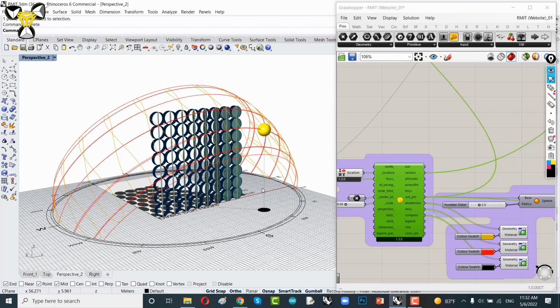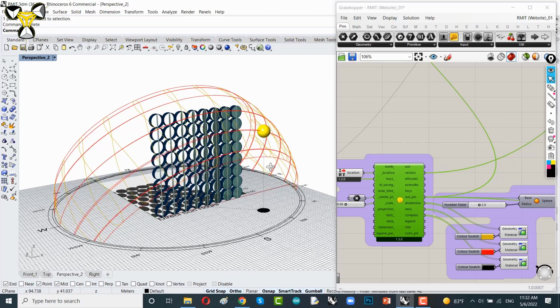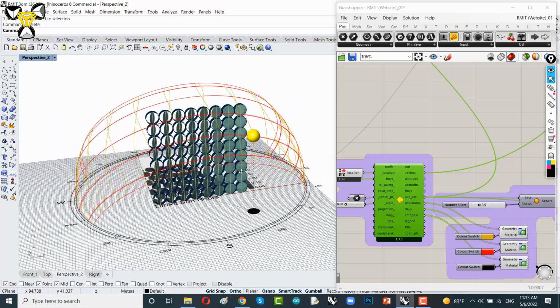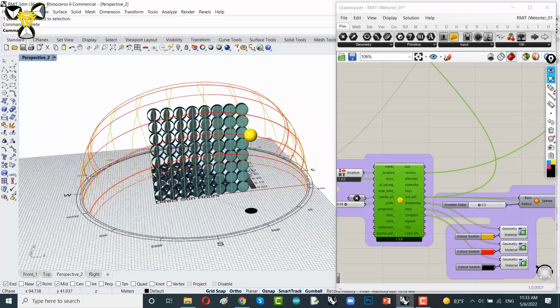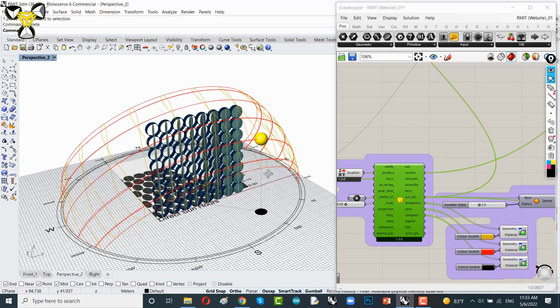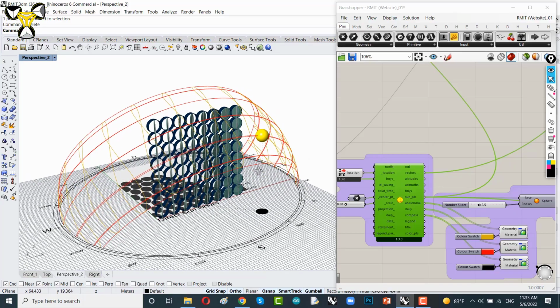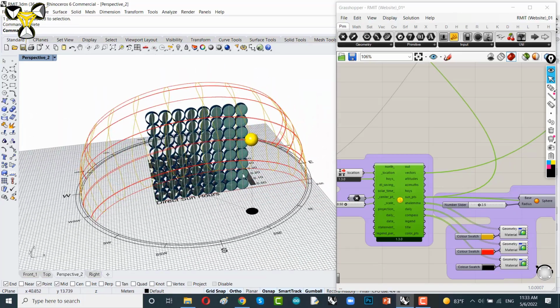Well, there are some different approaches to make a facade responsive to the sun's position. Indeed, there are some different strategies to control a dynamic shading system. Now, I want to talk about them. The most commonly used one is the Cutoff control strategy. In this control strategy, dynamic shading systems try to block direct sun radiations.